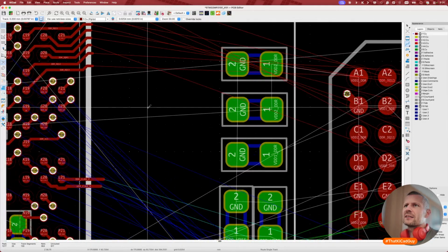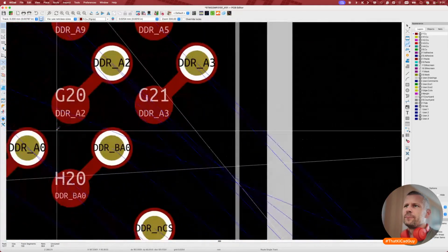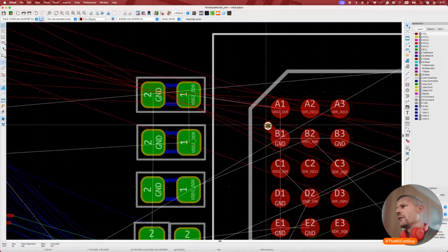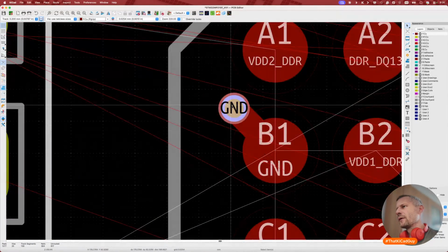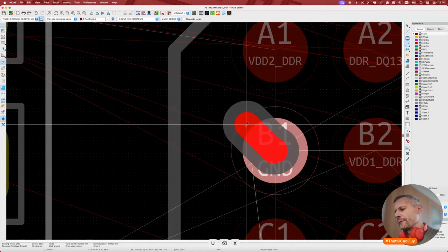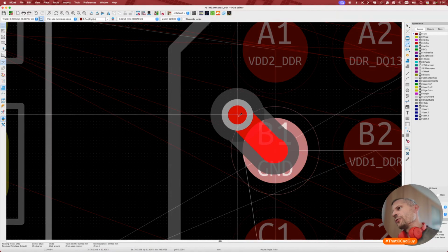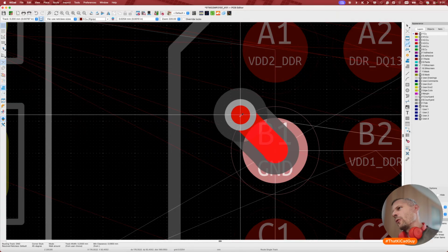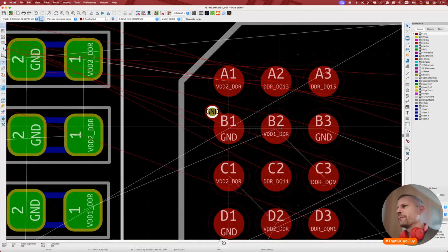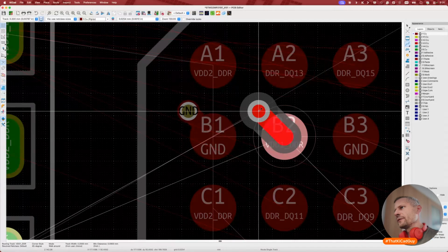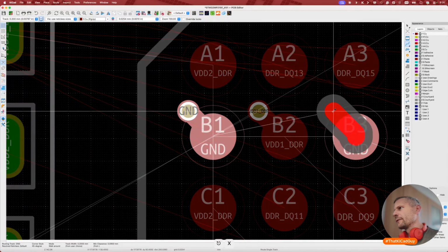Yeah, I verified last time that all the vias will be plugged, which is the standard technology of the 6-layer board as we are going to use. So I think this position is correct.